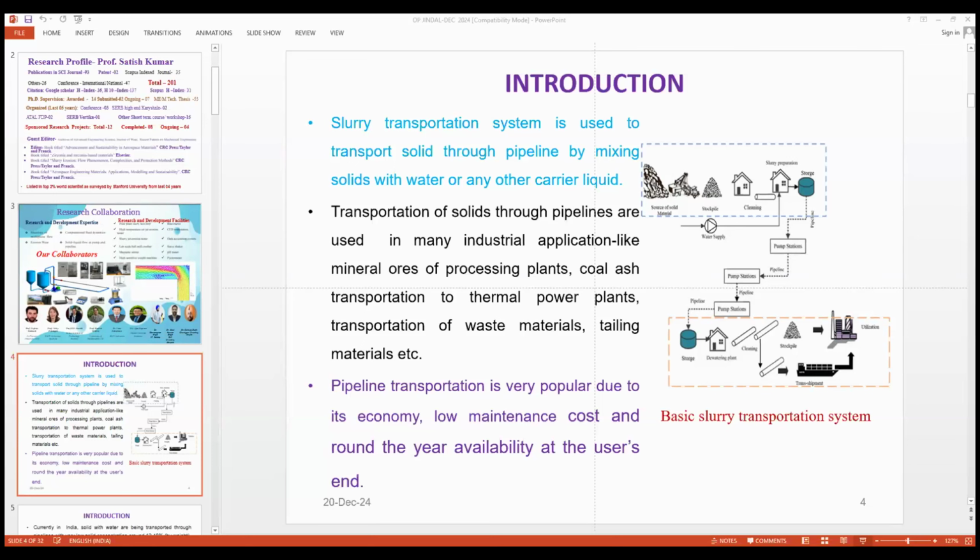First, for the modeling and simulation of the centrifugal pump, we disassembled all the components of the existing slurry pump setup, including the casing and others, and took the dimensions of the existing centrifugal slurry pump. This is called reverse engineering. With the help of plaster of Paris and other applications, you have to measure the exact dimensions of the pump, then prepare the 3D model. So these are the specifications of the pump components.